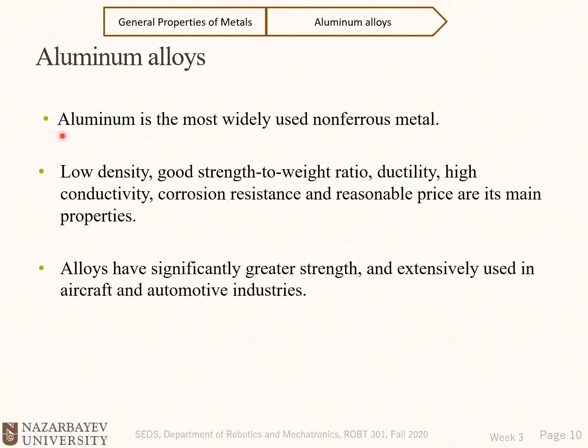Aluminium alloys. Aluminium is the most widely used non-ferrous metal. Low density, good strength to weight ratio, ductility, high conductivity, corrosion resistance, and reasonable price are its main properties. Alloys have significantly greater strengths and are extensively used in aircraft and automotive industries.